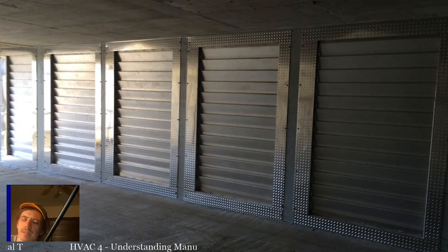I'd have to go back to the other PowerPoint. I think it's 5 microamps. I always got to double check it too. I want to say it's right around 5 microamps is usually the lower limit on that current reading. But 10 is about normal. You want to make sure that you're getting something in that range, not something real low like 1 or 2 microamps or something like that.